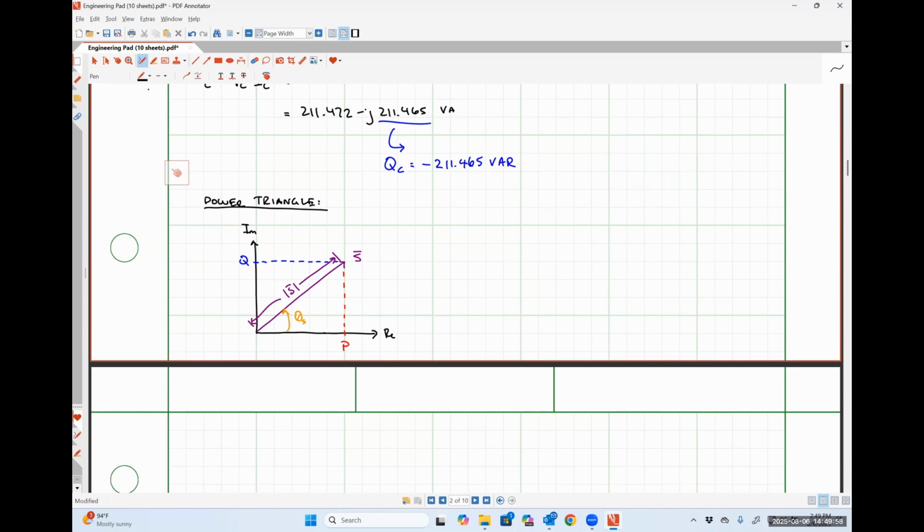So instead of using those several equations that we were given earlier, we can just say that our complex power S is P plus JQ in rectangular form, or magnitude of S angle theta S in polar form. So this is just another way to think about which part of complex power represents which thing. So if you can remember that the average power is the real part, then put your answer in rectangular form and just look at the real part.